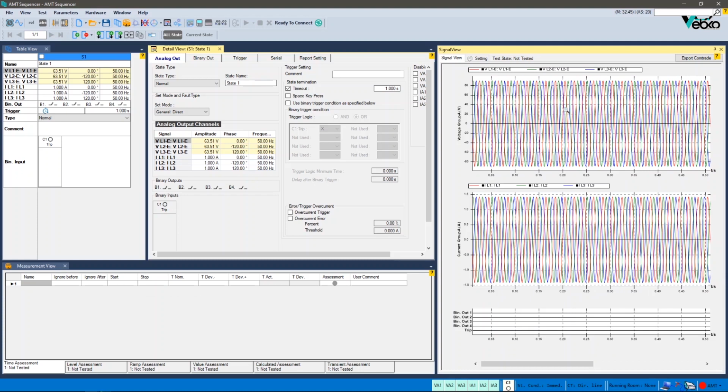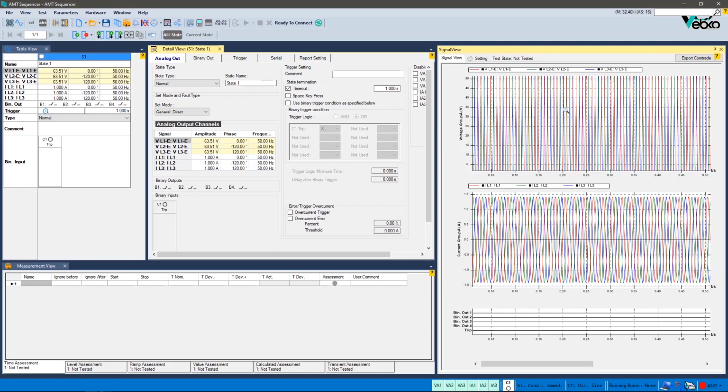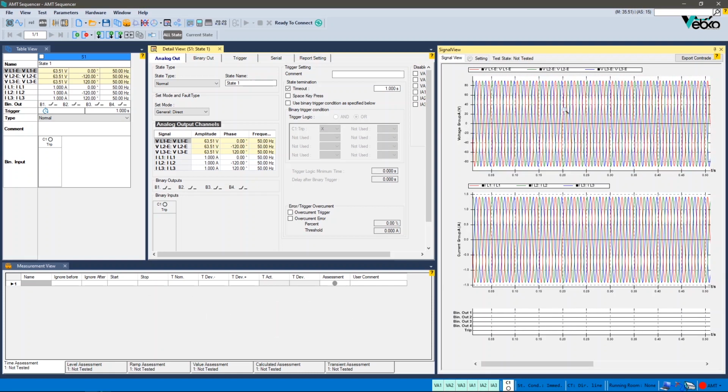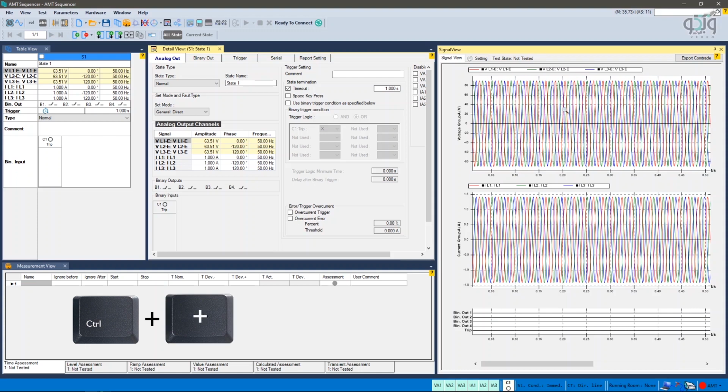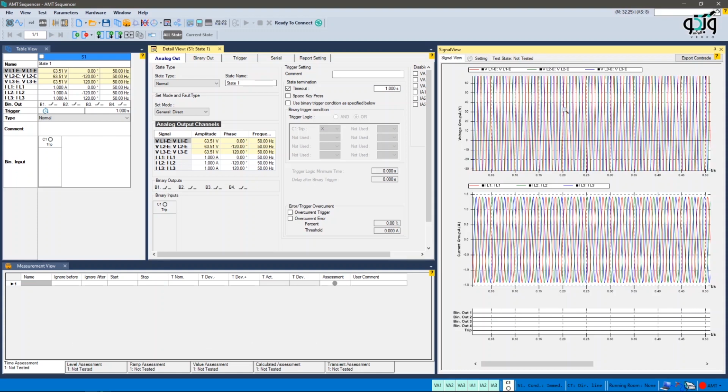In order to zoom along the vertical axis, hold down and roll the scroller. By holding this, you can zoom in on the voltage diagram of group A along the y-axis. This can also be done by holding down the control key of the keyboard and using the positive and negative keys. Using Optimize option, the diagram display can be optimized.